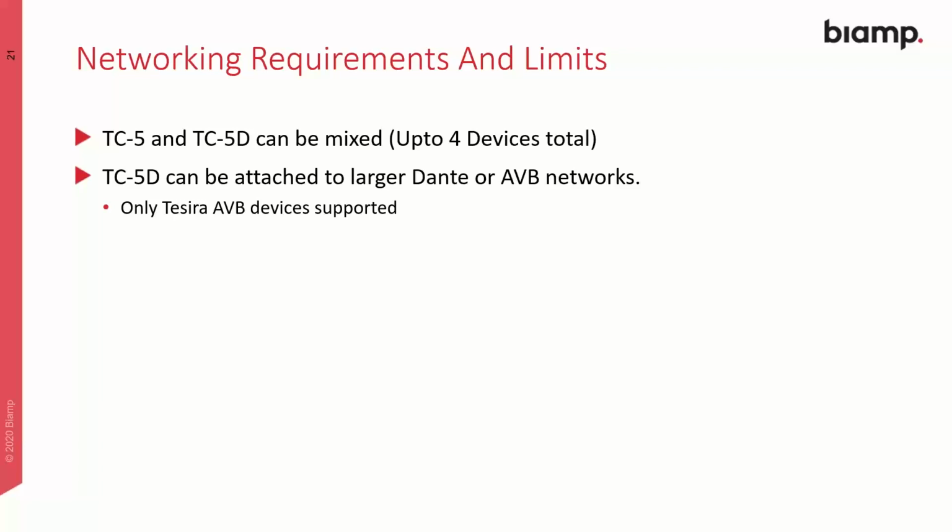And we just demonstrated that live in the demo. The slides also showed that earlier before the demo. Only Tesira AVB devices are supported, however, no third-party AVB. So Tesira AVB implicit routing and Dante networks are supported together. This will work pretty much with any supported AVB switch.